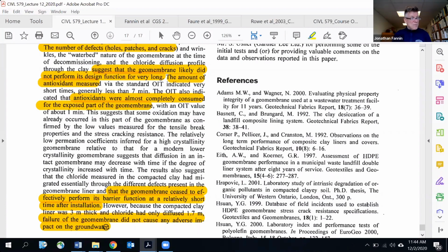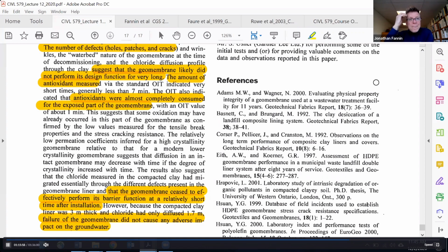And maybe the concept of a geomembrane as an adjunct to a clay barrier in some situations, and that you needn't necessarily, depending on the components of your system, have every component with the same service life for the system to perform. And there's an interesting philosophical point on which to draw a closure on issues of durability.